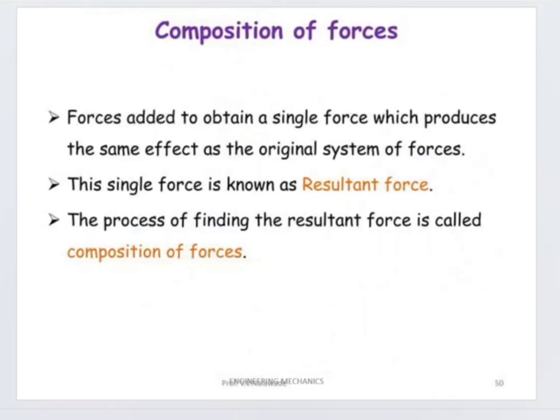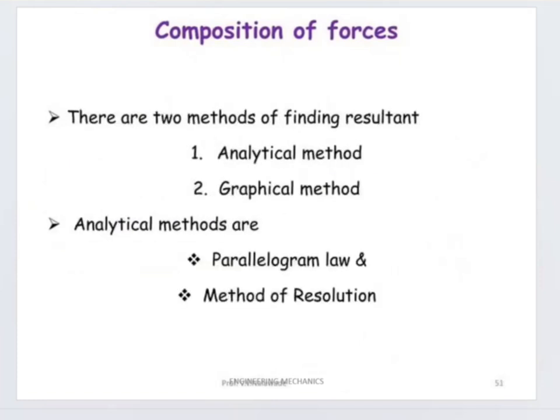So what is the meaning of composition of forces? Forces are added to obtain a single force which produces the same effect as the original system of forces. The single force is known as the resultant force, and the process of finding the resultant force is called composition of forces. There are two methods of finding the resultant: one is analytical and the second is the graphical method. In the analytical method, there are the parallelogram law and methods of resolution.